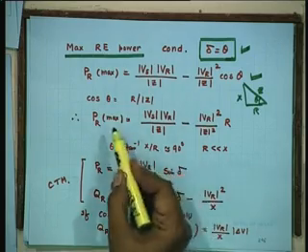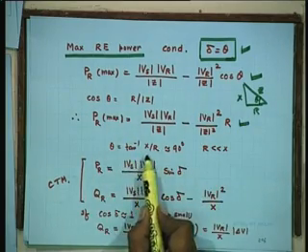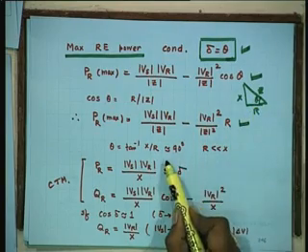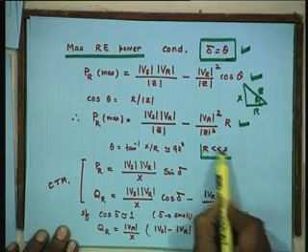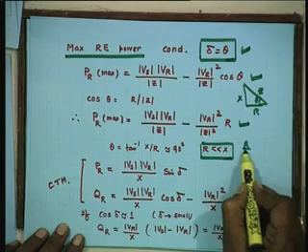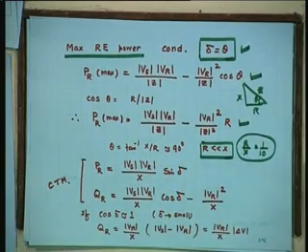So, the value of PR max is this, where theta is tan inverse x by r, same theta drawn in this triangle, roughly 90 degrees, as I said. Why? Because r is very small as compared to x. In fact, r by x is roughly 1 by 10.